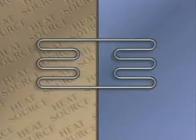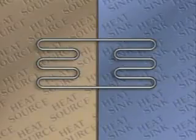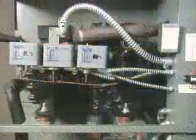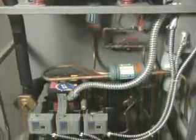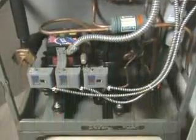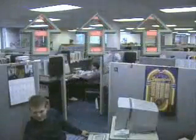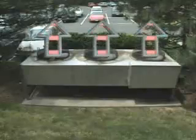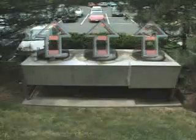The substance that heat is transferred from is the heat source, and the substance that heat is transferred to is the heat sink. Every refrigeration system has a heat source and a heat sink. For example, refrigeration equipment in this air conditioning system uses a refrigerant to cool an office space. The heat source is the air in the office space that is being cooled. The heat sink is the outside atmosphere, which receives the heat from the air conditioning system.